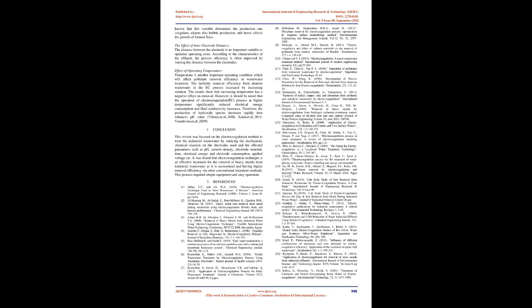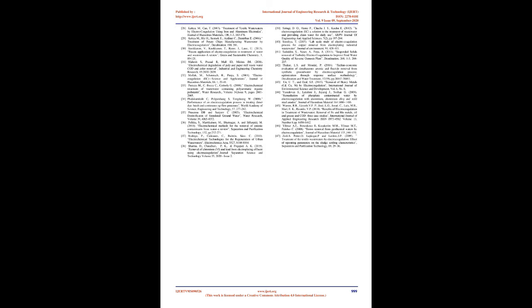The effect of electrolyte type on the removal efficiency using Fe and Al electrodes respectively in the presence of different supporting electrolytes including NaCl, KCl, CaCl2, NaF, Na2CO3, Na3PO4 was studied. Experiments were done using NaCl as it is cheap and the solution contains high conductivity, so it needs low voltage for electrocoagulation and hence it is economical on an industrial scale. Usually, NaCl was used as supporting electrolyte in the electrochemical process and KCl is used to obtain the conductivity in the EC process. Panitsa et al. 2000. Yang et al. 2000.